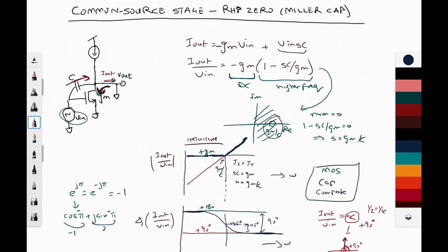So this is a right half plane zero, because the magnitude response rises and the phase falls. And this is an aside for a different topic, but that spells really bad news for control circuits, because you get magnitude that is rising, but then you get more delay, so that can lead to instability. But hopefully this video gives a quick intuition behind right half plane zeros, why they occur, and kind of graphically how they come about.